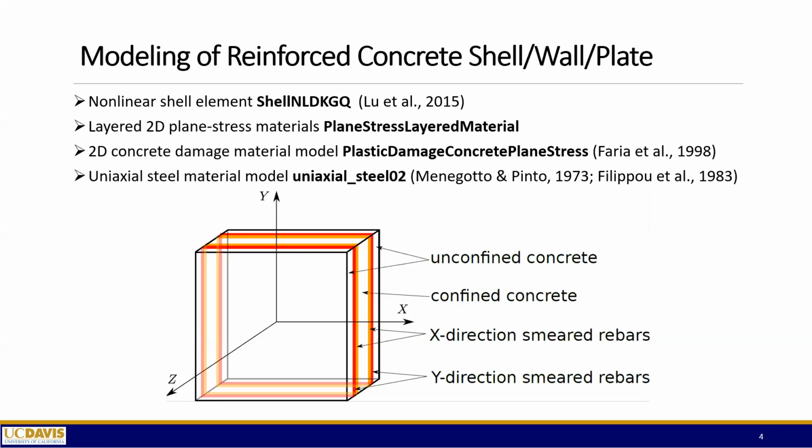So here the finite element formulation we are using is the so-called shell NLDKGQ. This element formulation was developed by Professor Lu from Tsinghua University in 2015. And coming together with it is the plane stress layered material that is used to combine all the different layers of material that I'm showing right here.